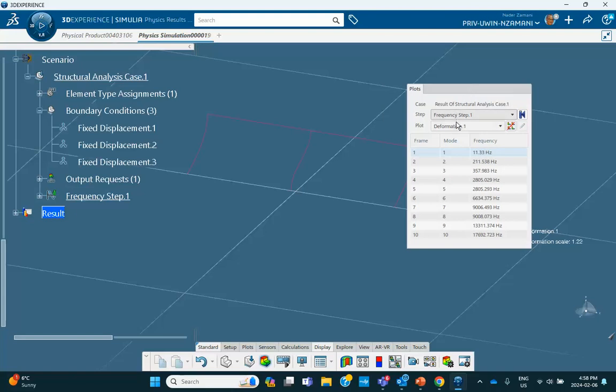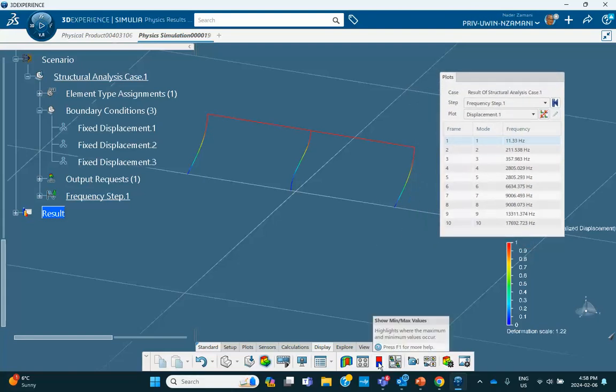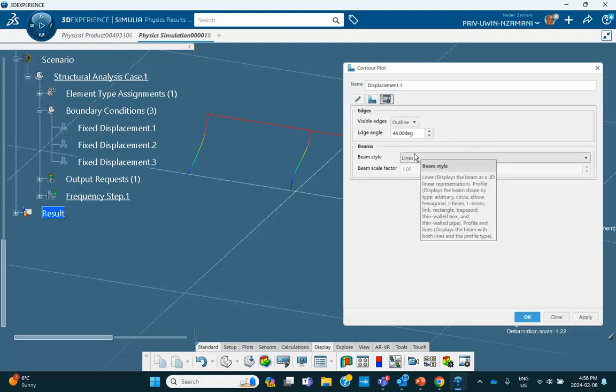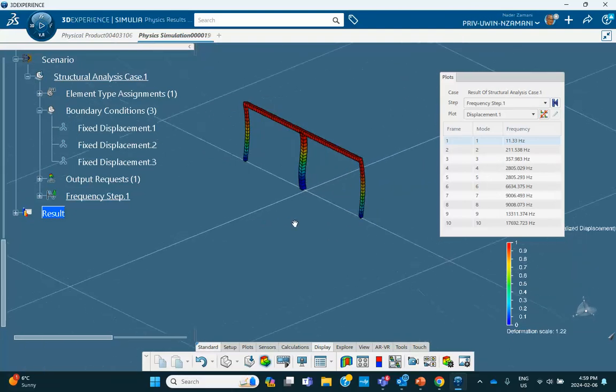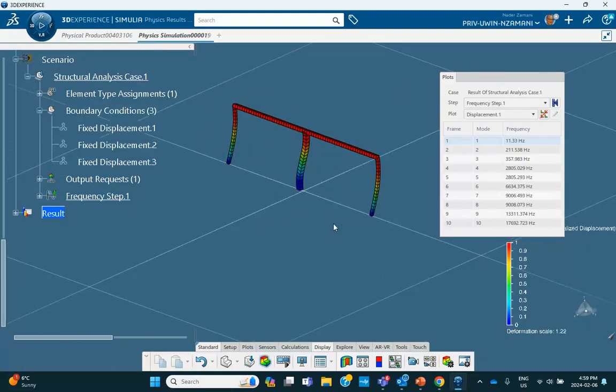So my mistake, I did a lot of mistakes. First of all, let me show you the displacement here. All right. And in case you want to see it in 3D, you can go under display mode and click on this. Click on these contours. This opens up. Select the last tab and say, show me the profile. There. Now, I made several mistakes. I forgot to tie these. That was number one. Then I forgot to put the restraint at these ends. Okay. So I had to go and fix it, and eventually we got it to work.